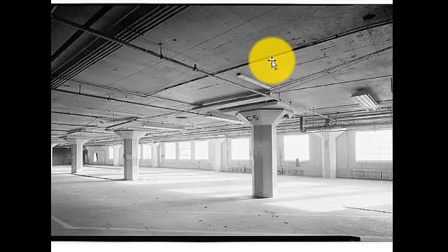I said it does not have a beam. So you should know that a beam will add to the height of the building. And since there are no beams, of course, the height will be reduced, and that is good. And number two, it is economical. Then the disadvantages: it requires many columns. You can see there are many columns here. Look at it. 1, 2, 3, 4, 5.